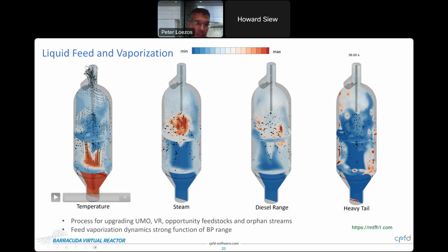So the feed, the hydrocarbon feed, which usually comes along with quite a bit of water, is fed to the reactor through this lance to a spray nozzle. So the feed is sprayed countercurrent against combustion gas, which is entering at the bottom of the reactor here. So the combustion gas is supplying the heat for cracking, and the cracked products, the upgraded products, along with the combustion gas, exits the top of the reactor and goes downstream for further processing.